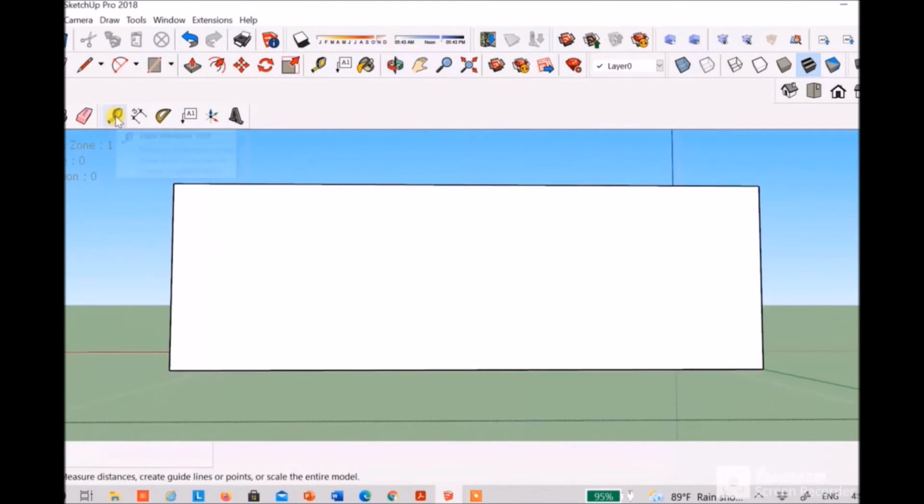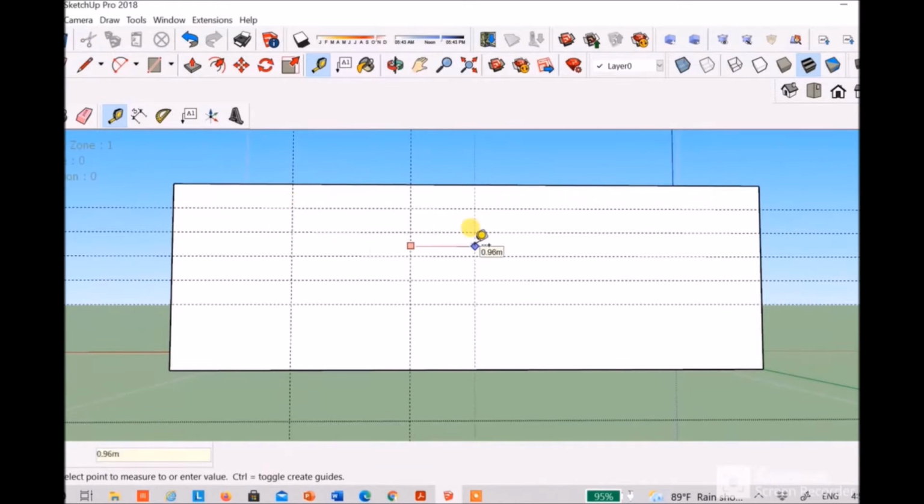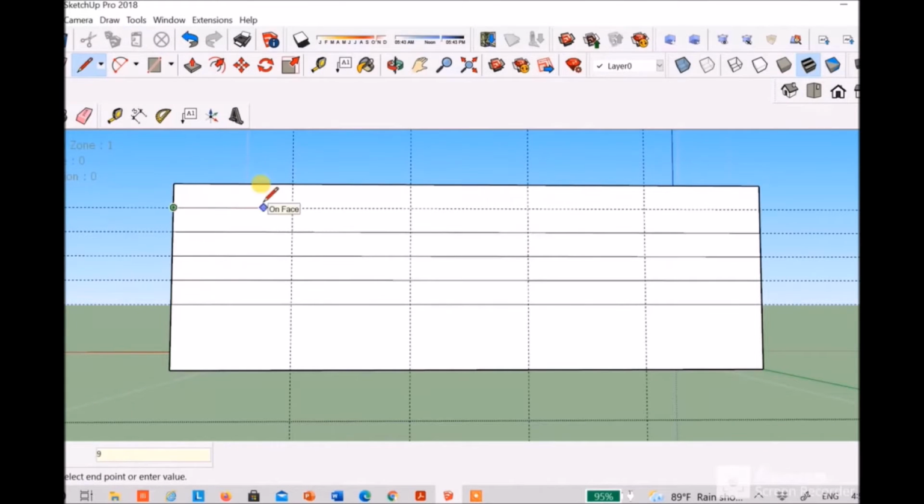This is wall 4 and it has 26 sections. This wall has 5 horizontal divisions of 0.37 meter each and 5 vertical divisions of 1.76 meter each. Similar to before, we draw the edges between the endpoints and we remove the extra lines that we used to create these subsections.